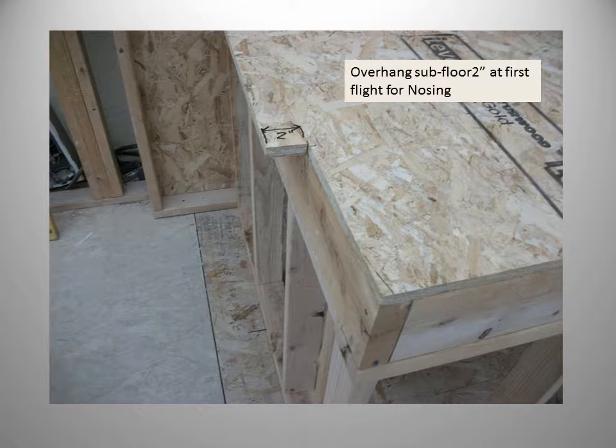Note, however, that we extend the subfloor over the lower stringers to create the nosing on the landing. We need to do this since the application will be with carpet and the landing nosing will need to protrude the same as our treads. The upper floor subfloor should protrude in the same manner so that all treads and landings in the stair have the appropriate nosing overhang.